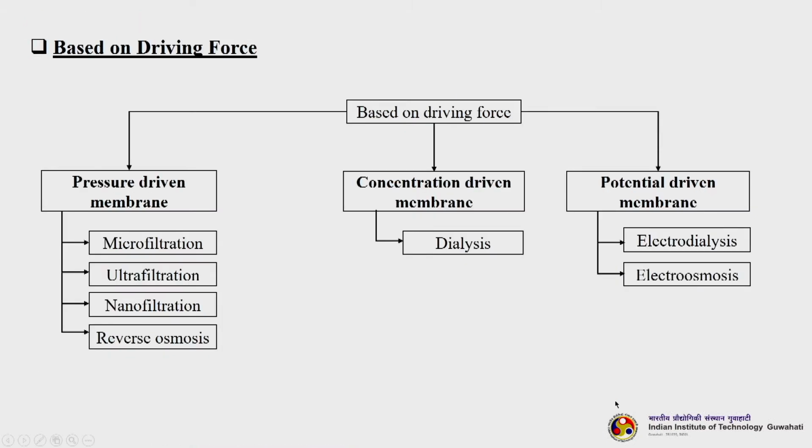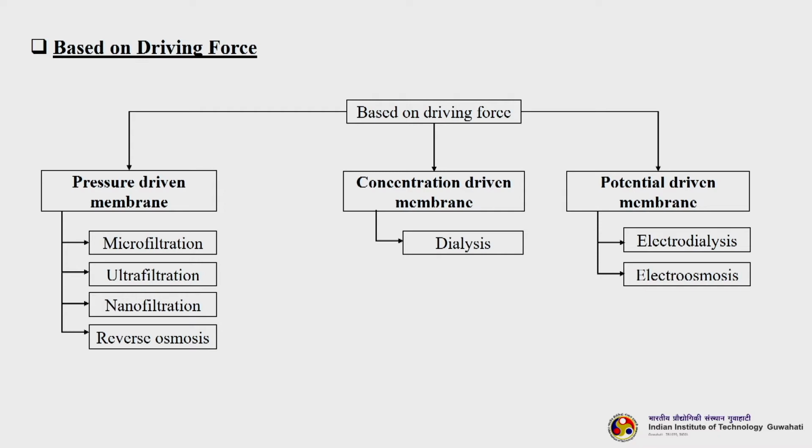The next one is based on driving force. We can have 3 different types of classification under this particular sub classification. We can have pressure driven membrane, under which microfiltration, ultrafiltration, reverse osmosis and nanofiltration come. Then we can have a concentration driven membrane, under which dialysis and hemodialysis come. Then we can have a potential driven membrane, which is electrodialysis and electroosmosis, basically under the influence of an electric gradient.